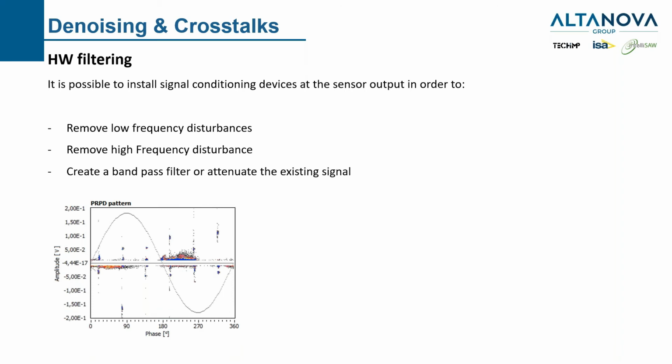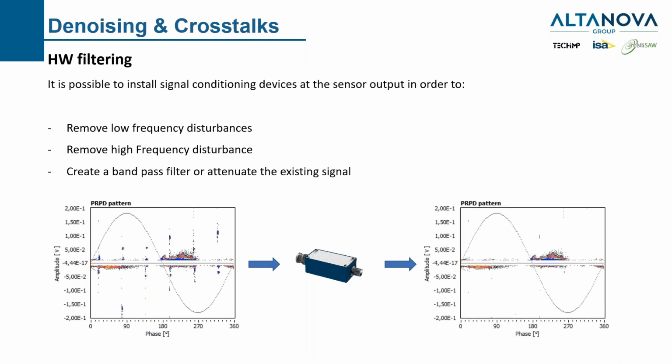Here we have a case with a full acquisition where we have a PD and exciter noise together. If we make this signal just pass through our hardware high pass 2.5 MHz filter, the signal will be more clear. We have lost the frequency components belonging to lower than 2.5 MHz, sorry, but we will have all the rest very highlighted. This is very important, in my opinion, if you want to correlate amplitudes. We shall measure the proper amplitudes, not the exciter amplitudes.